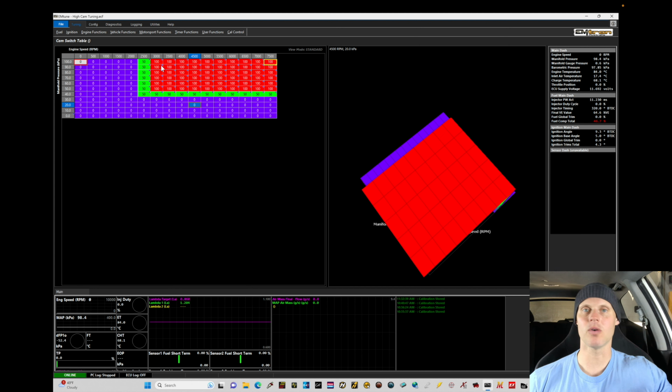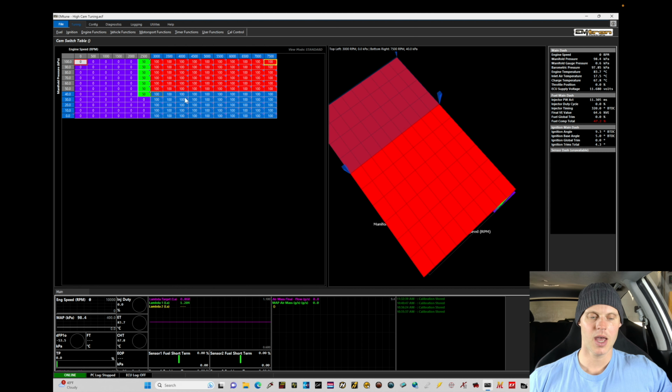Now we're going to set our dyno up so we're going to be staying at least 3,000 RPM or higher during our pulls, so we don't have to worry about dropping out of VTEC. Then when we do our part throttle mapping, we're also going to be in VTEC, and we're going to be doing that above 3,000. What I'll actually do here is just set this to 100, even in my...